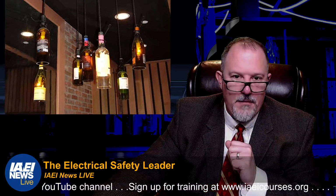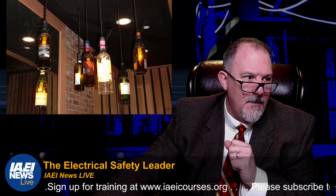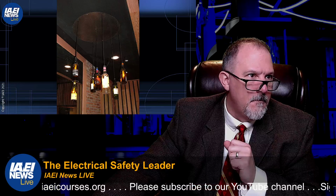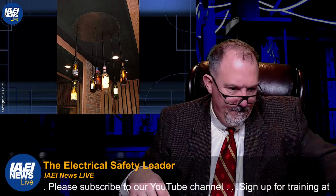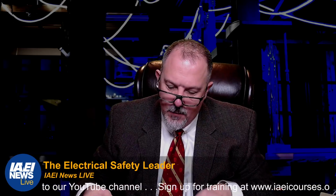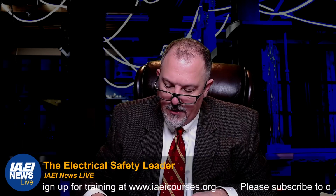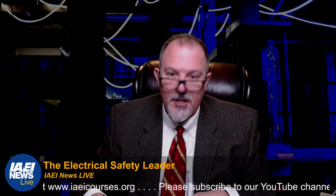What helps us prevent installations and misuse? What helps us prevent that? The beginning of 410 helps us. In 410.6, listing required, all luminaires, lamp holders, and retrofit kits shall be listed.